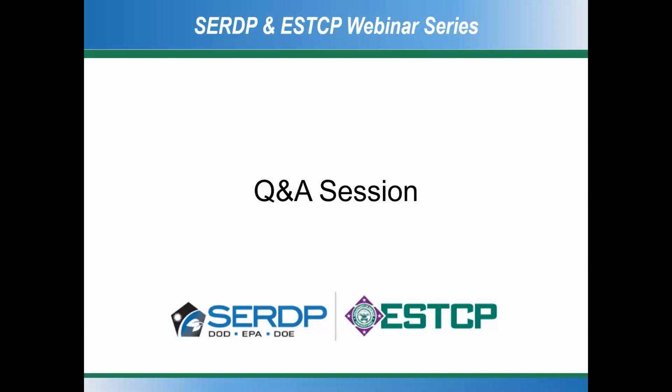So now the first general question for you is, what are you working on next with respect to this project and other DoD microgrids? Yeah, so Raytheon has continued to work in this space, and we have a few ongoing projects where we're still focused on battery storage microgrids and controller hardware in the loop methods to develop and demonstrate these types of technologies. And one of the limitations on this system is we have one battery that, when the system is performing, if that battery fails, then the whole system fails. But other concepts we're pursuing allow us to distribute that functionality to multiple batteries in order to provide similar levels of resiliency to networked diesel generators and diesel generator centric microgrids.